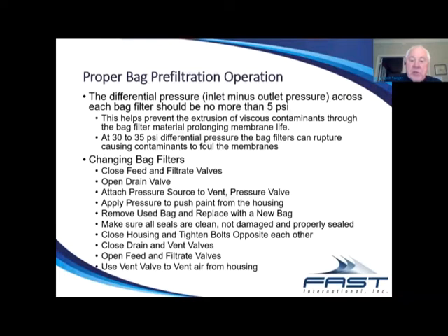Make sure all the seals are clean, not damaged, and they're properly reset. Tighten the housing by tightening the bolts, and do it cross tightening, as you would do with a tire on a car. Close your drain and vent valves, open your feed and filtrate valves, filling the housing full of paint. And then I'd recommend opening the vent valve, without air pressure on it, so that you get the air out of the housing.